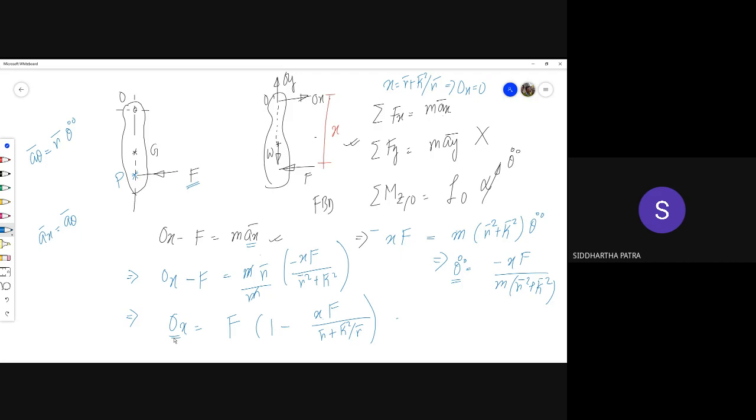Essentially their wrist acts like a pivot point, and they don't want their wrist to be damaged, right? They would want minimum reaction at their wrist. So in order to do that, they would try to hit the ball with the center of percussion.